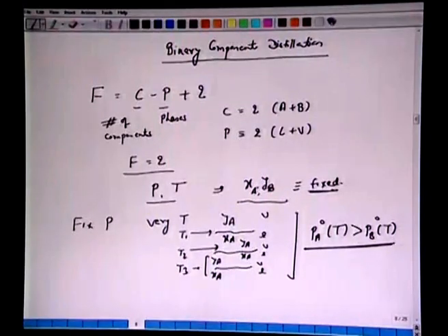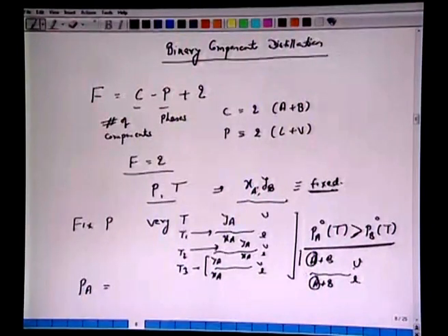There should be a significant difference in the vapor phase. Quantitatively we will do the calculation in the coming classes, but the idea here is that one can apply Raoult's law for the partial pressure at equilibrium between the two phases, vapor and liquid, A plus B here and A plus B here. This vapor phase is rich in A and lean in B, relative to the liquid.